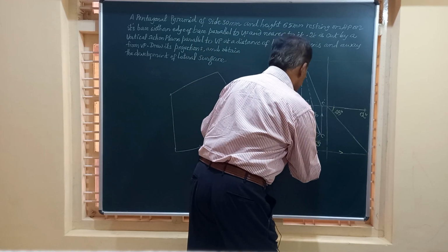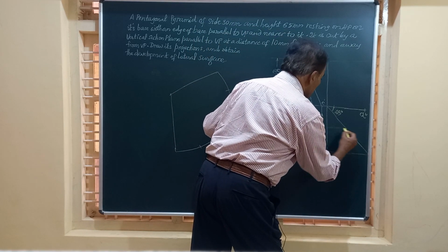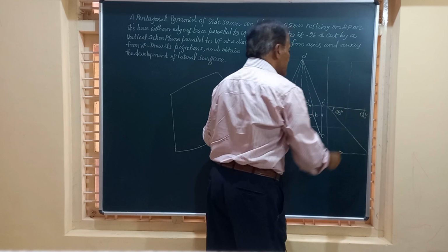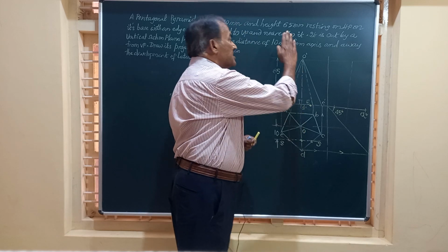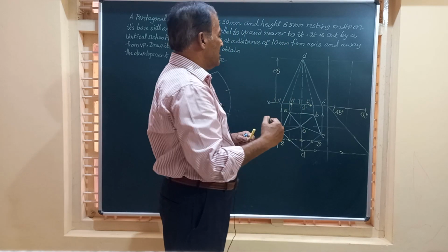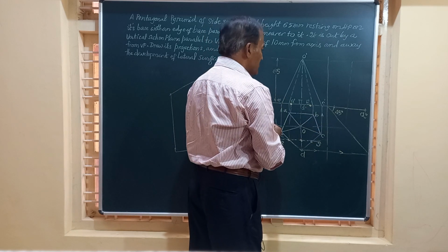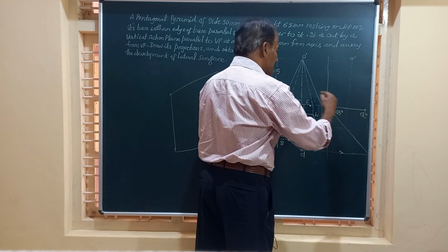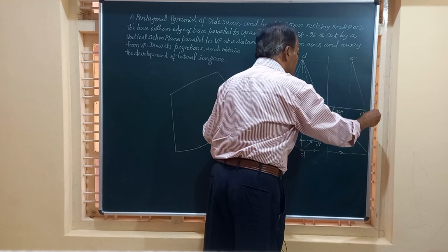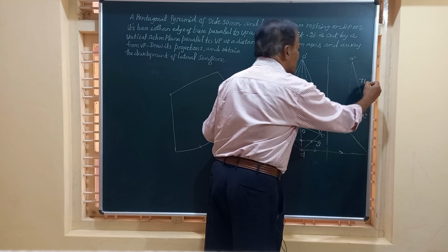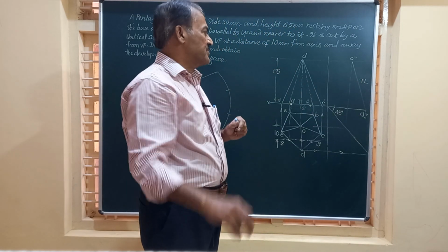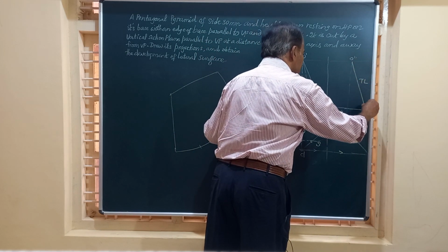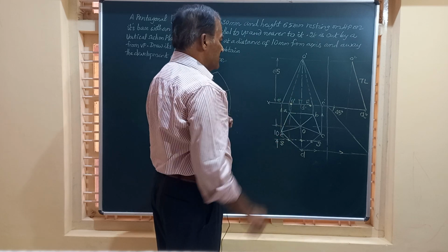So let us get what is called the vertex or the apex of the solid. This is the apex of the solid. Listen carefully, friends. This OD is inclined to wall just like a ladder inclined to wall. And this will give you the true length here. So friends, in the end view, this is D double dash, this is O double dash. And if you join these two, you will get what is called the true length of this slant edge of the pyramid. I will just mark it dark so that you can see clearly. So this is the true length you have got, friend.